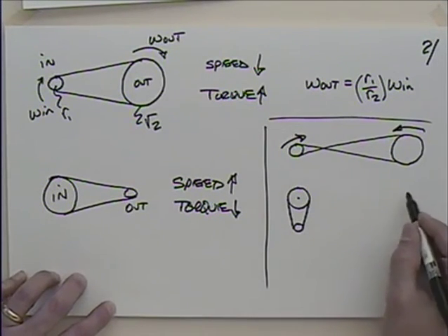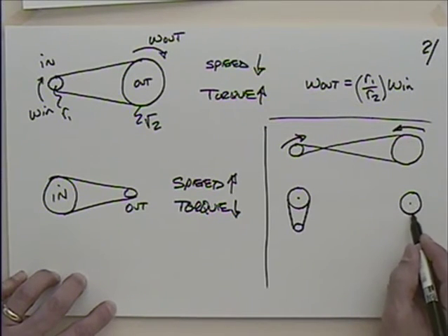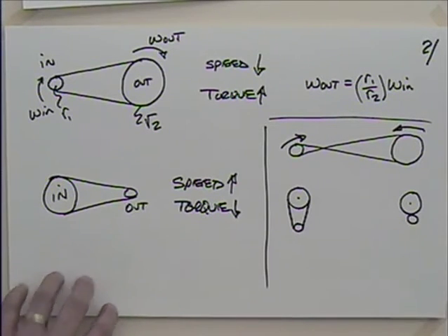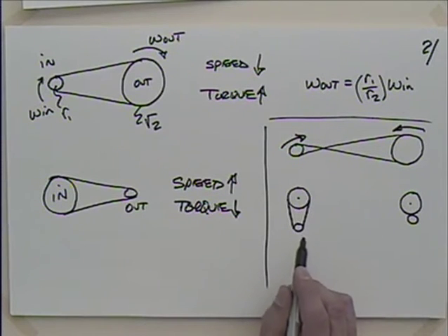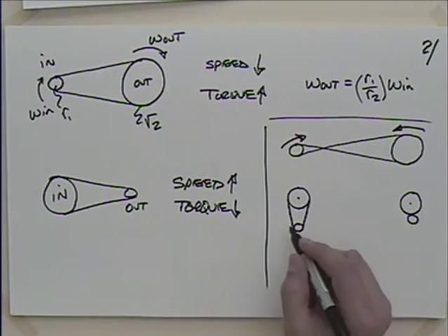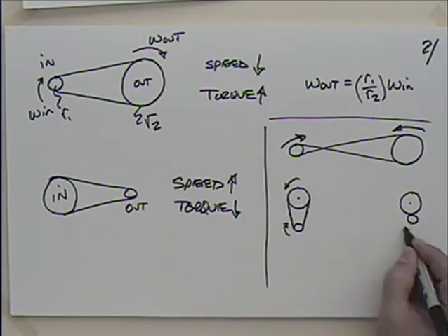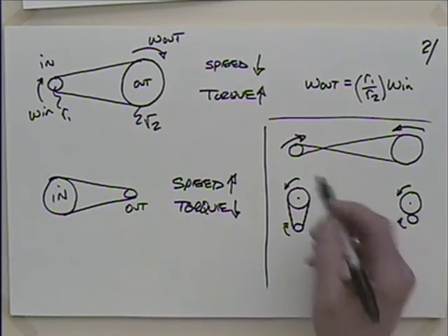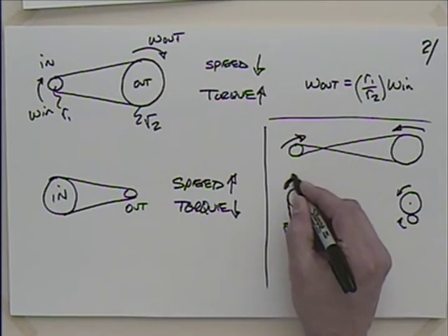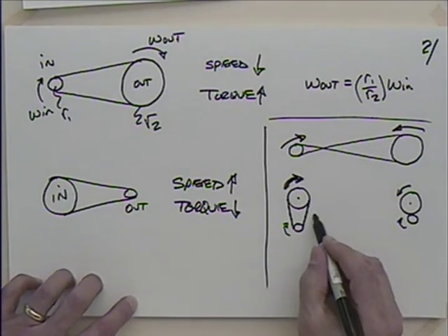And in industrial engines, they will have gear-driven camshafts. The gear on the camshaft will look like this, and the gear on the crank will look like that, and it will be gear-driven. Now, we couldn't probably just change this to that, could we? Because what's going to happen with the direction? Yeah, if this is going clockwise, this is going counterclockwise, isn't it? Whereas this is going clockwise, and that's going... Oops, I got this messed up here. This is going the same way, isn't it? Whereas these are going opposite directions. So how could I get a gear setup for this one?